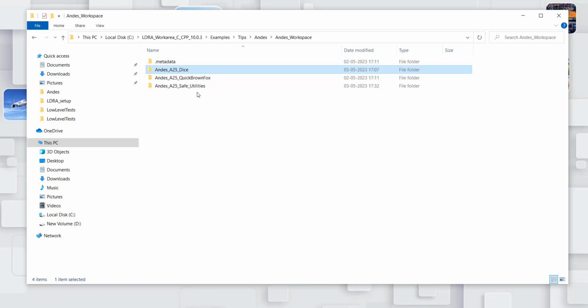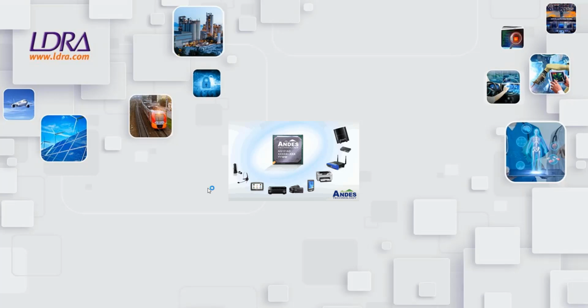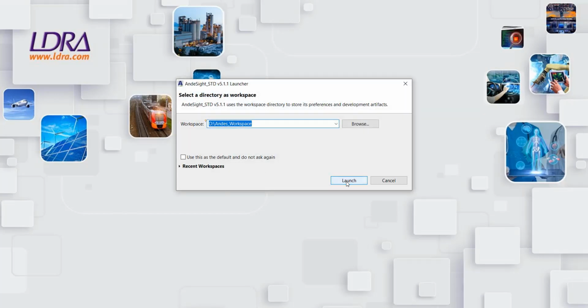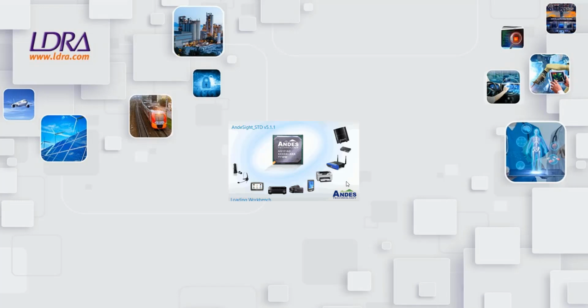To start with, we need to make sure that we open the example projects which are delivered along with the tool suite, and we need to make sure that we can compile these projects using the Andes environment. So I'm going to invoke the AndeSight IDE where my projects are located. I'm just opening the project from the appropriate work area location.